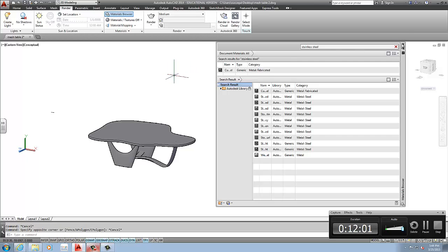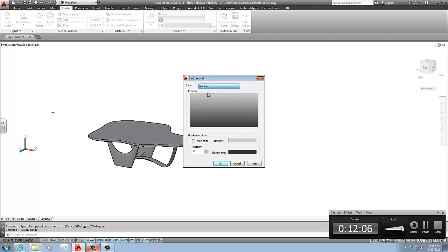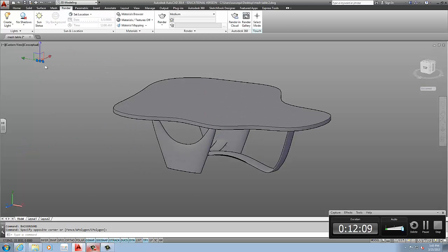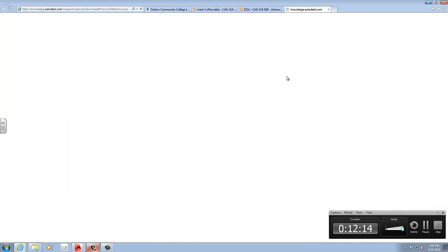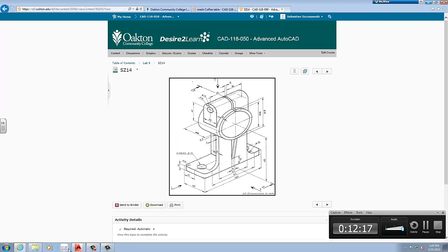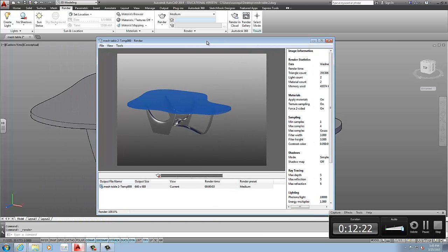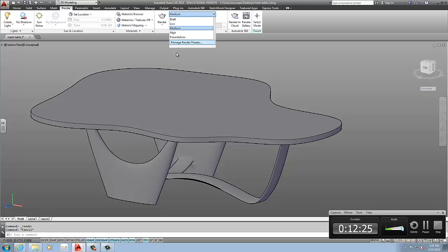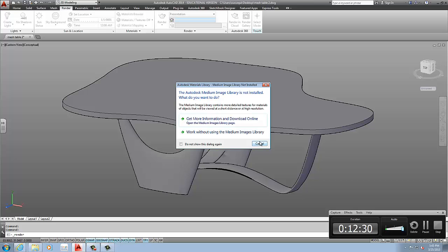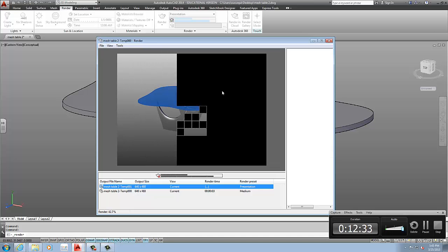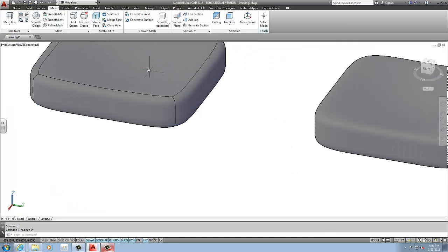Let's say I'm happy with a particular object, like this semi-pillow. Right now I cannot print it, it's not an STL, it can't be saved in STL, it's completely hollow, and it's not even a surface. So what I can do, with a copy of this for a second, is convert this into a solid. As long as it's completely enclosed, I should be able to do that. All I need to do is go to Mesh, and there is an option to convert to solid. So I select the object, and it converts it to a solid part.